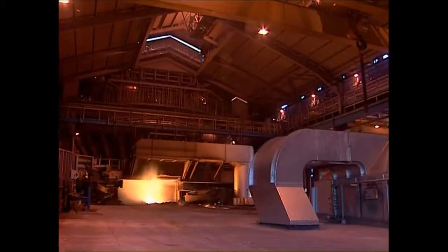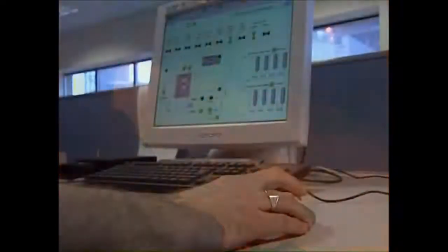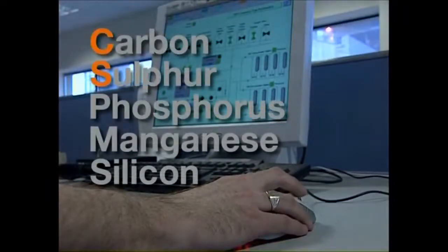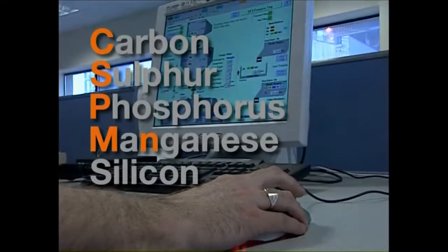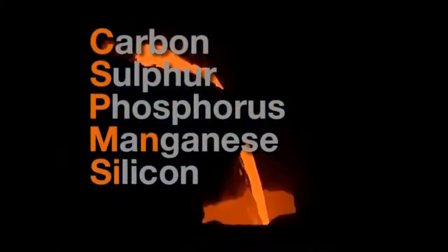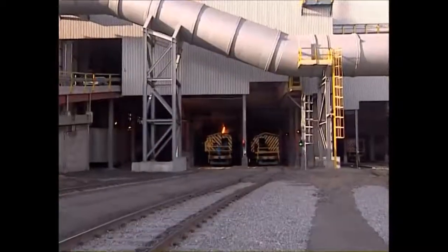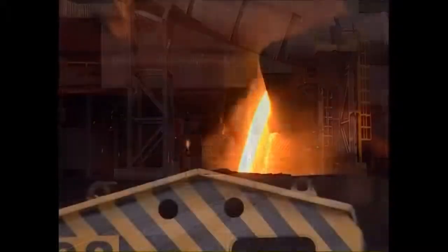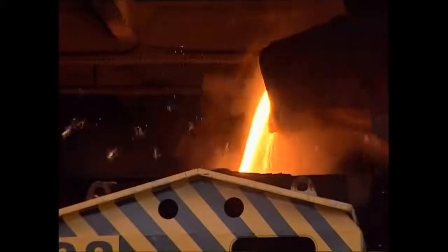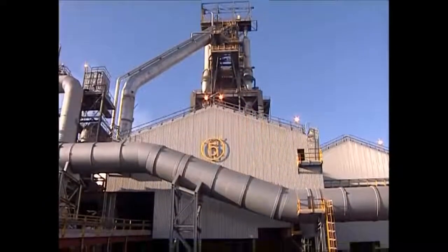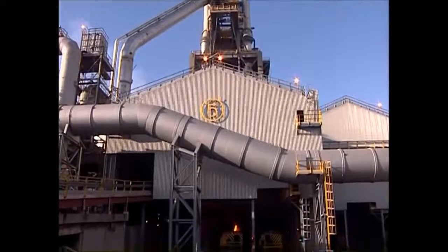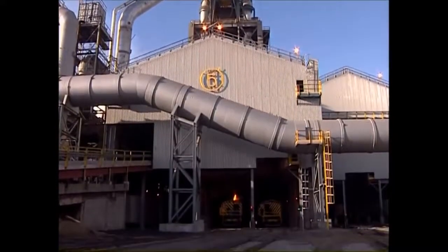The molten iron we get from a blast furnace, or hot metal as it's known in the industry, isn't pure iron and contains the elements carbon, sulphur, phosphorus, manganese and silicon. To make steel, these elements must be removed or reduced and other elements added depending on the type of steel being made. The carbon content, at about 4%, makes iron very brittle and unsuitable for rolling or forging, and although iron can be used for castings, most of the iron produced is for processing into steel.